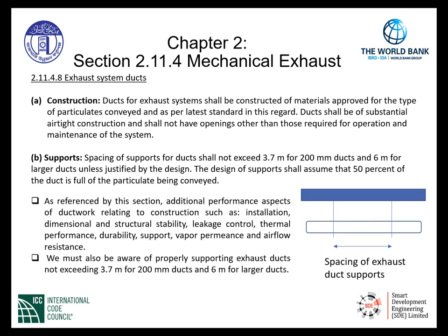We must also be aware of properly supporting the exhaust ducts, not exceeding 3.7 meters for 200 millimeter ducts and 6 meters for larger ducts. As seen here on the right-hand side, the graphic, proper support is required and we are given a maximum spacing interval according to this particular section.